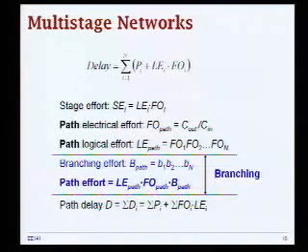If you have perfectly symmetric case where everything is totally symmetric, and you know for sure that all the gates that branch have identical gate capacitance, fine, do this branching theory. Otherwise, you have to be very careful. And that's what you are going to learn in the project, how to optimize paths with various load that have the same delay constraint. And you will end up with different x1, x2, and x3. Okay?